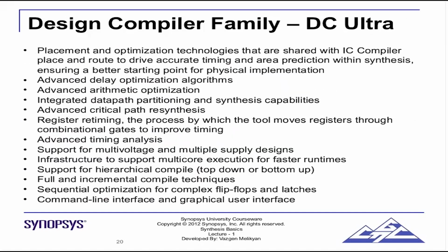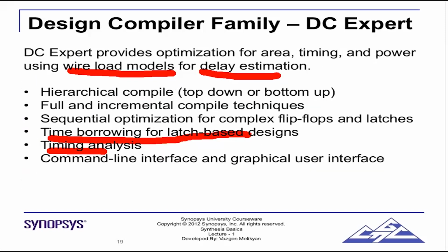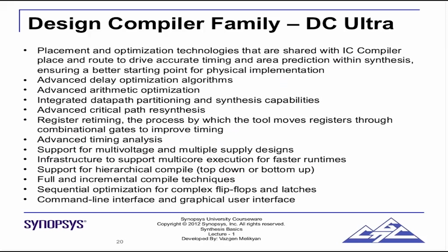DC Expert is the basic synthesis feature. The advanced one is DC Ultra. What is being used in industry is DC Ultra. It is a much more advanced version of DC Expert. Apart from what DC Expert does, it does advanced arithmetic optimization and advanced delay optimization.